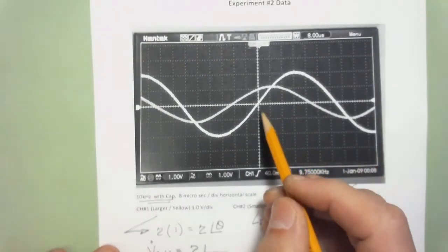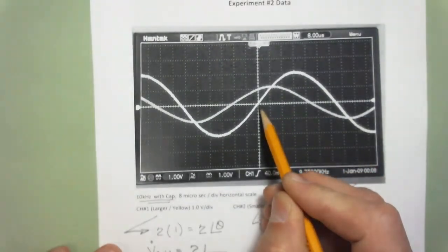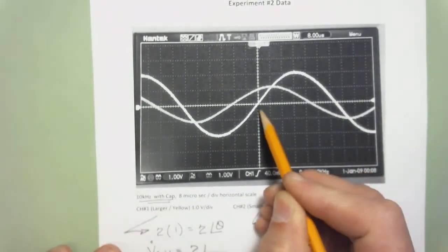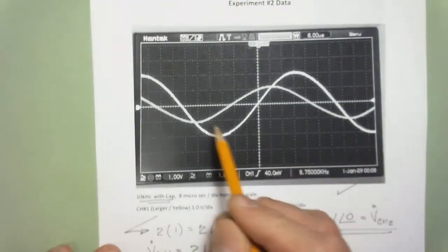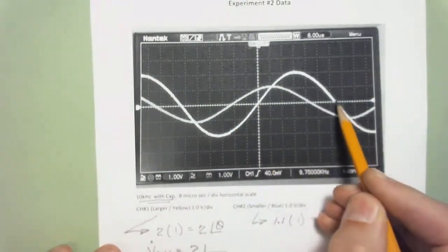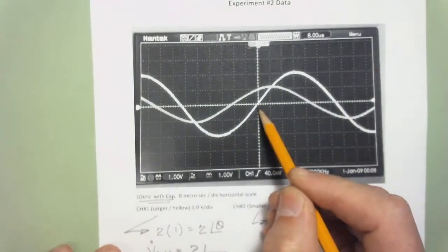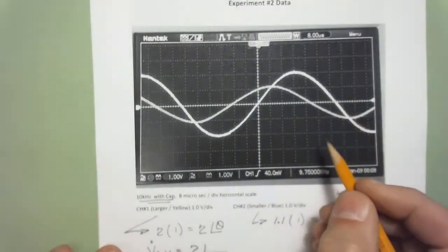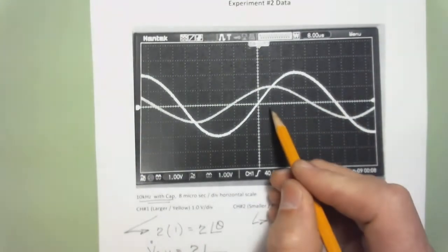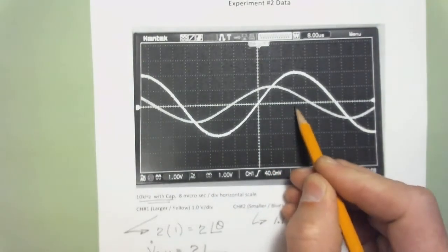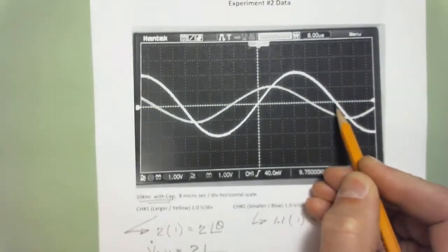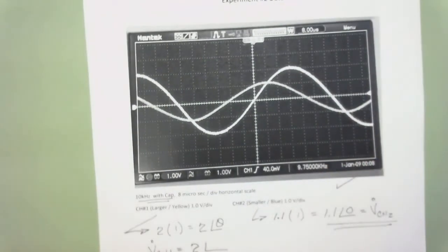So I think I'll go ahead and figure out the frequency here, that's an intermediate step that we're going to need. I'm just going to use this wave here, and I'm just going to look at 180 degrees of this. I mean, you could do the whole thing. You could measure from there to there, and that's 360. I like the way this is pretty close to 0. And so I can just measure 180 degrees there. So let's count that up. 1, 2, 3, 4, 5, 6. It looks like I've got 6 and some change. I think I'm going to call it about 6.4.